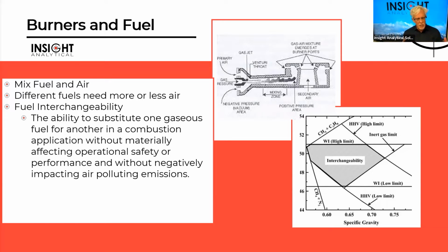In things like gas turbines, we can actually damage the turbine by running too rich a fuel to it. And so it's important, you'll see, and we have Jochen on here from Amatec, the hydrocarbon dew point analyzer, that a lot of people who are putting in large compressors would put a dew point analyzer up there in front of it to try to ensure that they don't get too rich a fuel into that engine because of the potential problems it can cause.